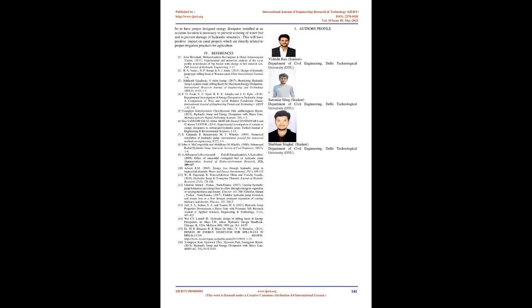Conclusion and future scope. This paper shows an experimental study based on energy dissipation in hydraulic jump through different methods like stepped weir and screens. Experimental results have clearly shown that using step size with ratio of height of step size to height of breaker equal to 0.8 produces maximum energy dissipation.